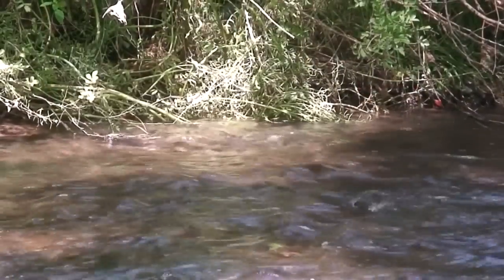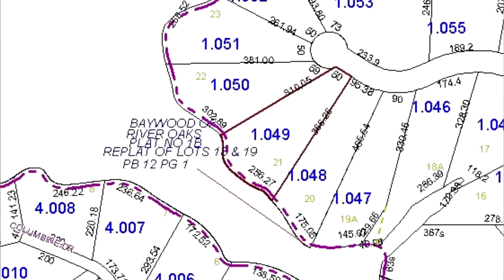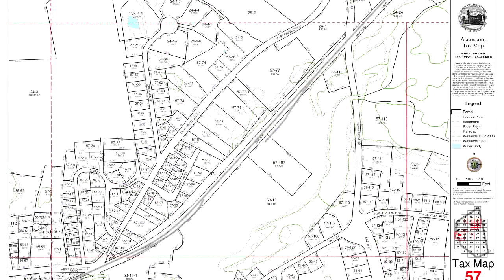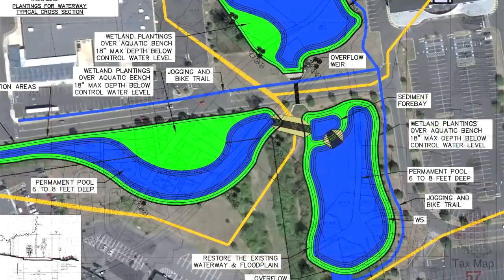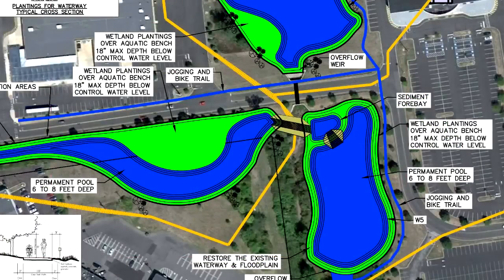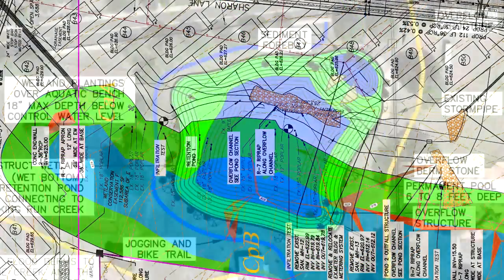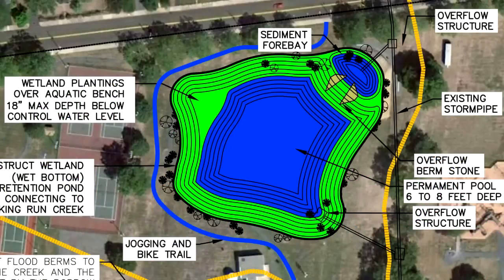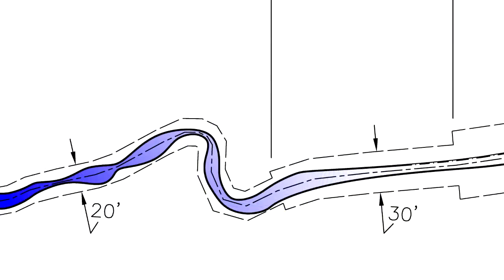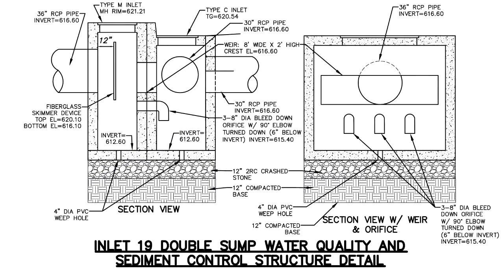And these drainage pipes are where the most concentrated pollution is flowing into our rivers, lakes, and streams. All waterways have easements over them, protecting them from being developed any farther. These easements must be defined and studied to determine what size treatment pond we may construct there. The larger the easement, the bigger, more natural pond we can install. The smaller the easement, the more likely we have to construct a small structural type of system.